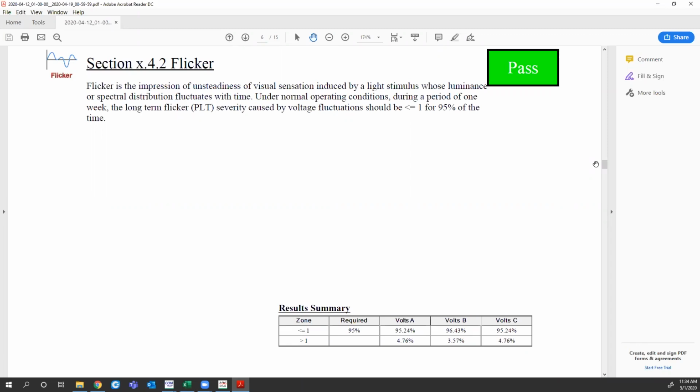You could have flicker and not notice the brightening and dimming of fluorescent lights. It is a long-term cause of eye strain, which can cause eye problems in the future. That's why people are starting to use flicker monitors to check to see if lighting loads need to have some sort of protection or line conditioning to eliminate the brightening and dimming effect.